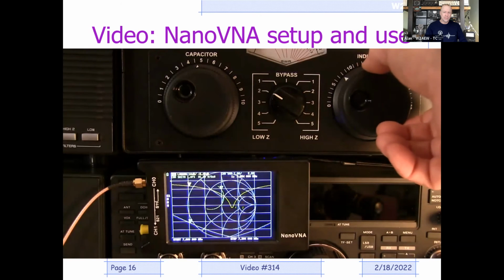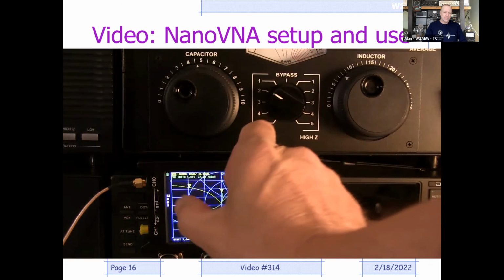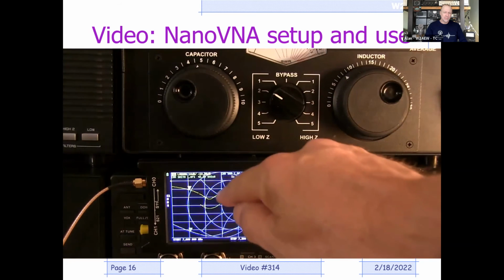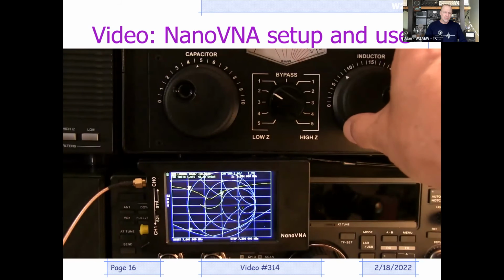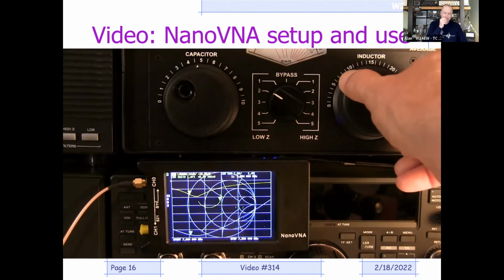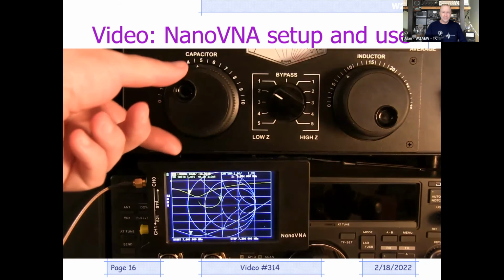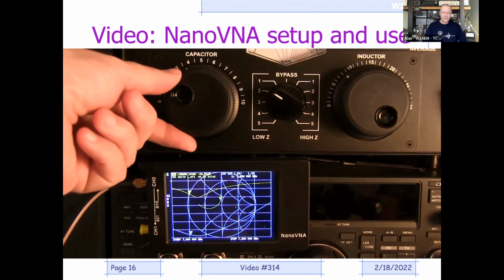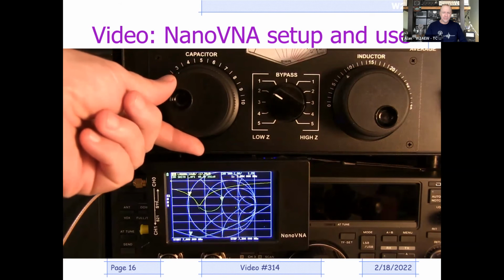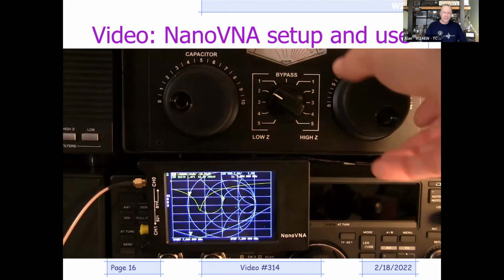We can see as I turn my inductor up, the Smith chart's kind of turning around in this direction. And we can actually see I'm bringing my marker on the Smith chart closer and closer to the center of the Smith chart. So I'm getting kind of close. But it's still kind of missing the mark a little bit, so we're probably going to have to optimize the capacitor here as well. So if we tweak on that a little bit, I can see I'm deepening the null there on the reflection coefficient, and I'm getting pretty close.